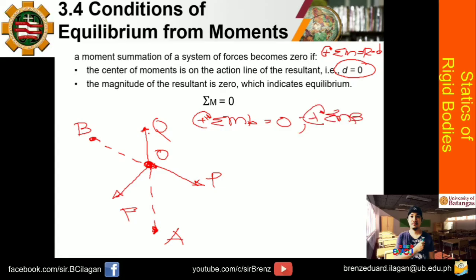So it must not be assumed that yung equation na yan, yung moment A and moment B, present two new additional equations of equilibrium. So they are really equivalent to summation of forces X and summation of forces Y. They may be used in place of or in combination with these equations as may be convenient. Thus, so ang ibig sabihin nun guys sa statement na yun, so yung summation of forces X and forces Y lang naman is equivalent lang din doon sa moment.